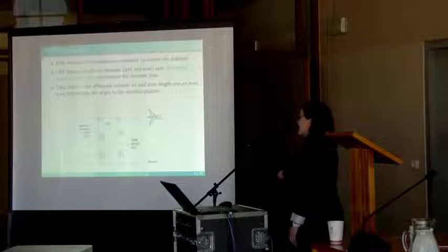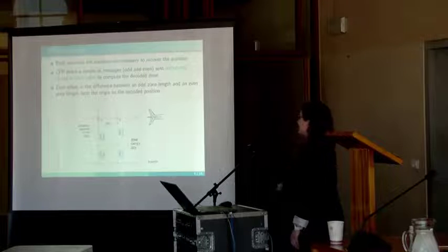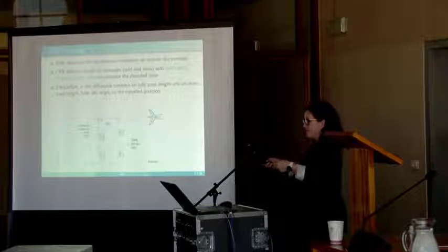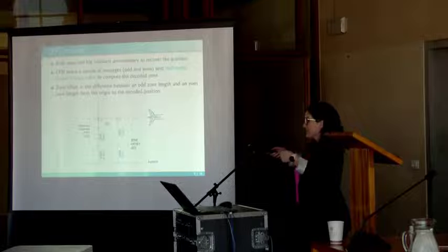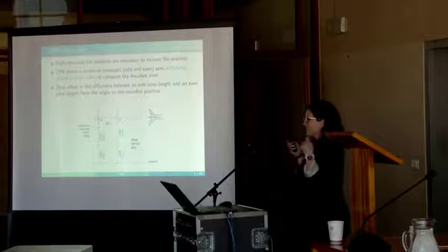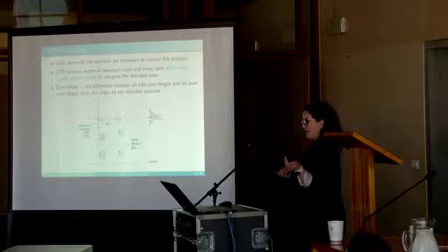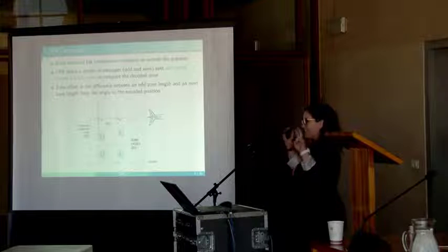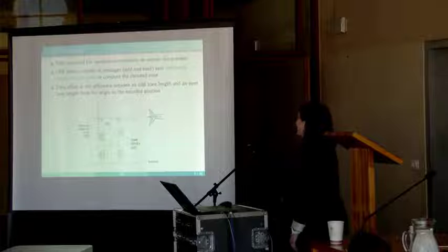Well, the CPR decoding will actually need 2 messages to recover the position. For doing this, it will use 2 messages, one even and one odd, so 2 different encodings that need to be sent sufficiently close to each other.